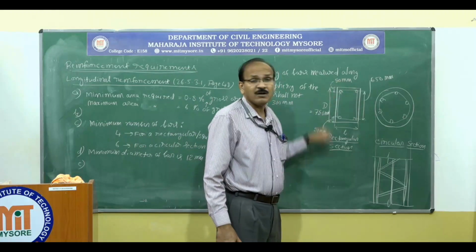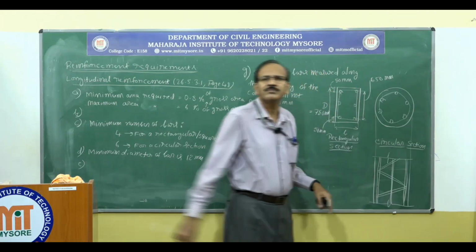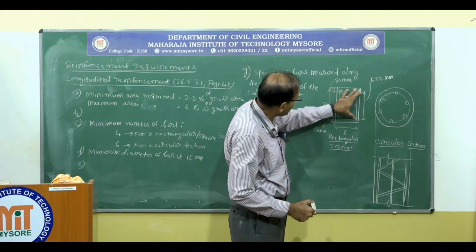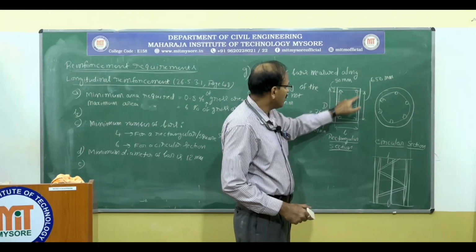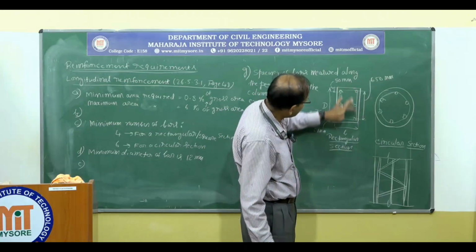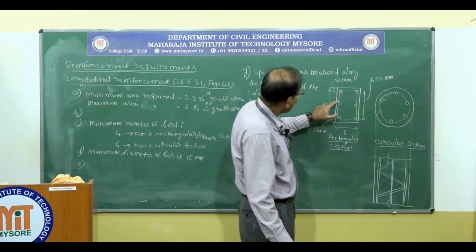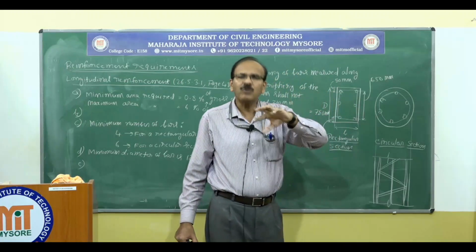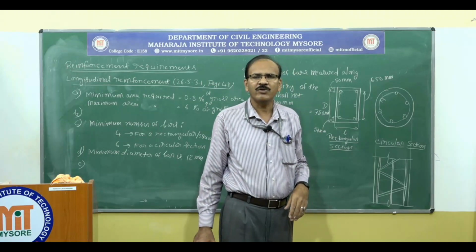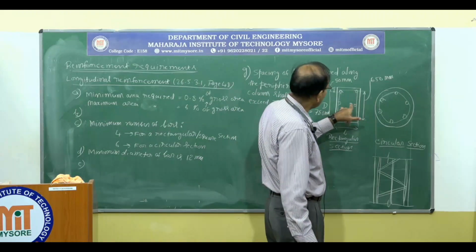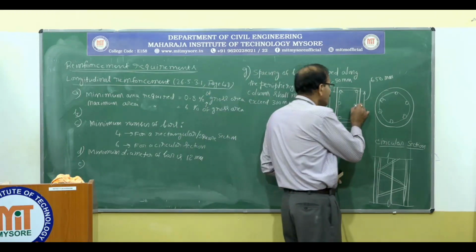This is the periphery of the column. So in this case what we do is, say let me put one bar, because when we are picking up the bars, instead of taking a higher diameter, if you need say 20 mm diameter 4 bars, if you put 4 bars at the corner, if this distance is 650 millimeter for example, then what we do is, instead of providing 4 20 mm bars, we are going to go ahead and provide say 6 16 mm bars. So in such cases, we are going to put 2 bars here. So in this case what happens to the center to center distance?